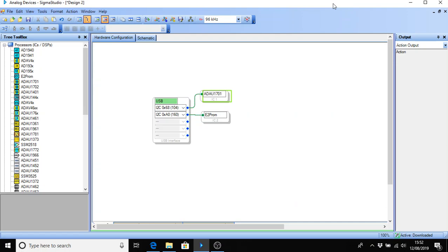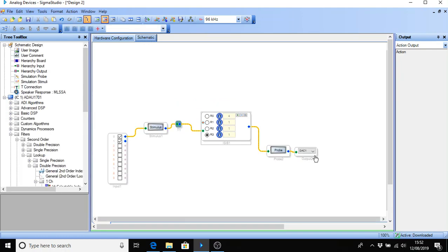So that's made the configuration correct. That's done that bit. We did use a DAC1 output. We'll revert that to DAC0, which is the output that we've been using so far. And now we have to select the filters. Now if I just look at this probe for a second,